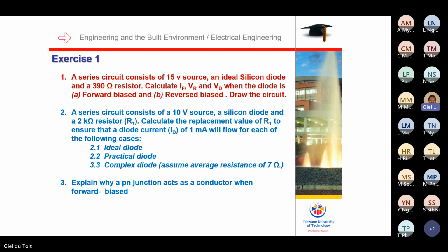Okay, so I hope you can see how to do this kind of problem. So my value here will be, because I must still have 1 milliamp flowing, 9.3 divided by 1 milliamp. Sorry, it's minus 7. Minus 7, guys. I made a mistake. Because 9307 minus 7 is 9293 ohm. My value will be 9293 ohm. That's what my value will be, the replacement resistance for R1. So in all three cases, it's different resistance. And this type of problem, you must be able to do. Okay. I'm done with this.